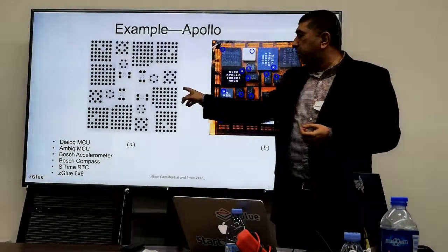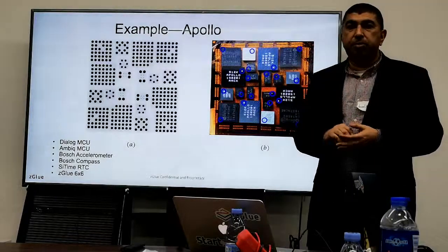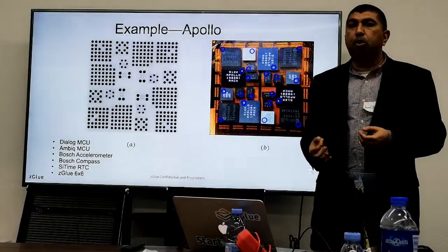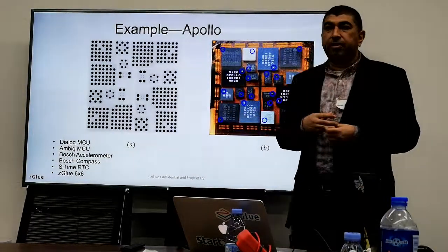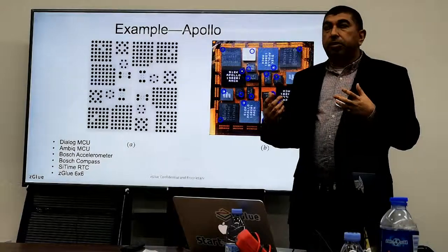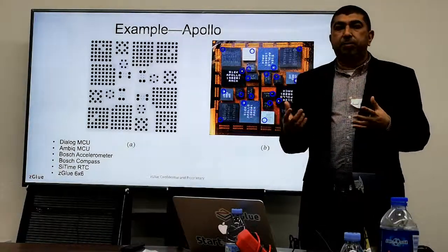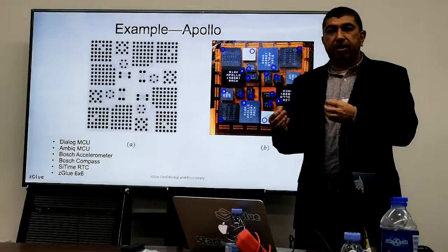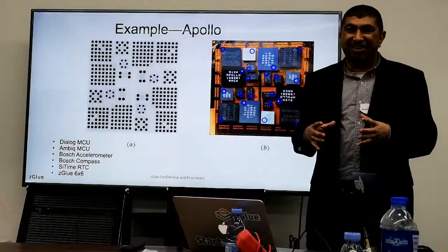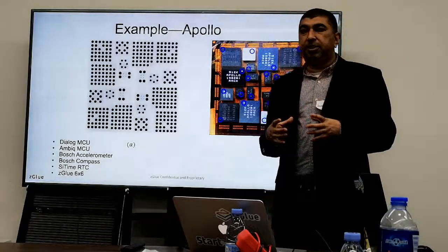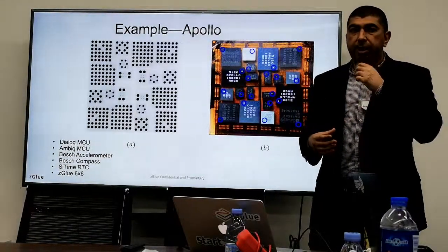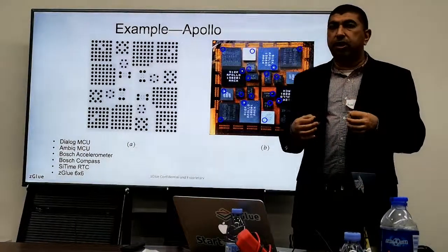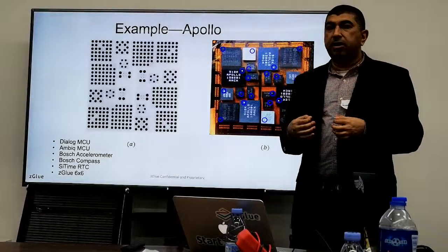In some cases, you can buy them down to 100 micron, 200 micron, but generally, the ones that people sell to go on boards are kind of limited to this. So you cannot go out there and ask people to create a special chiplet that is very standard. Every other chiplet has a different footprint, right? No two chiplets will have the same. There is an effort by a number of companies right now to standardize it, but it's gonna take another 3-4 years before it gets standardized.